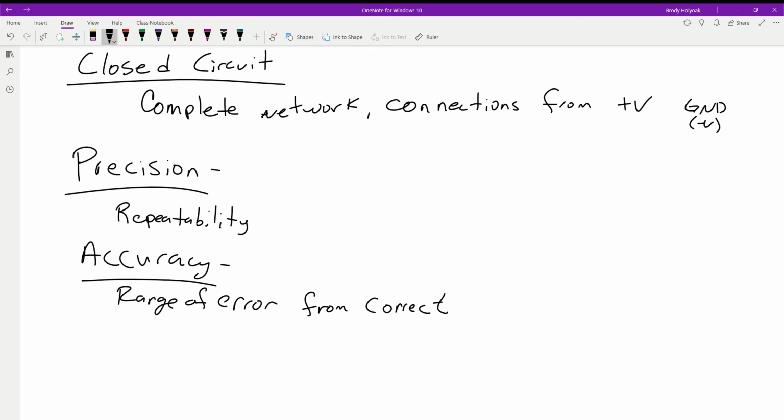Sometimes, if your precision is good, it just takes a little bit of nudging, a little bit of pushing you in the right direction. Maybe you're not quite using the right values. Maybe you're using the nominal value for the resistor when you should be using the measured value for your resistor. That's one of the differences too, like in lab. And that's why I'm harping on this a lot, especially early on. Use your measured values for your resistors, capacitors, that kind of stuff when you do your calculations.